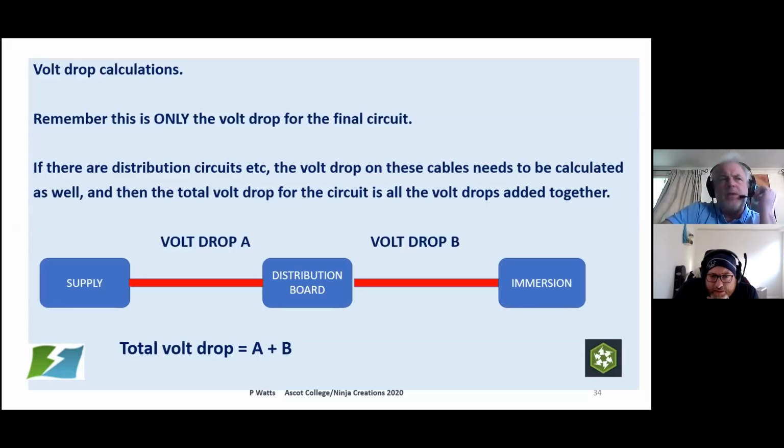I think James is talking about the parallel paths, whether or not you keep parallel paths when you're testing. Quite often, it's almost impossible to get rid of them, to be honest. Well, you've got to finish at some time, haven't you? To get meaningful test results from your calculations, you want to eliminate the parallel paths. If you can do that so that you can double check your test values against calculations, fantastic. But remember, obviously, that when the installation is under use, all those parallel paths are going to be there,